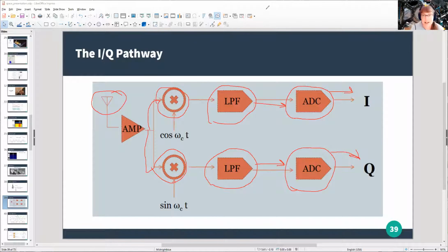And you'll see this a lot in SDR. And that confused me so much when I started SDR. There was this IQ, like save IQ data. What's IQ? Well, now you know. It's the way that we get data into the SDR so it can pass through the bandwidth of something like USB. And all software-defined radios, I don't care if it's in your Wi-Fi system or your phone, they all do this. They all take in a raw signal, multiply it by a sine wave and a cosine, and then get I and Q out. And that's what they work with.